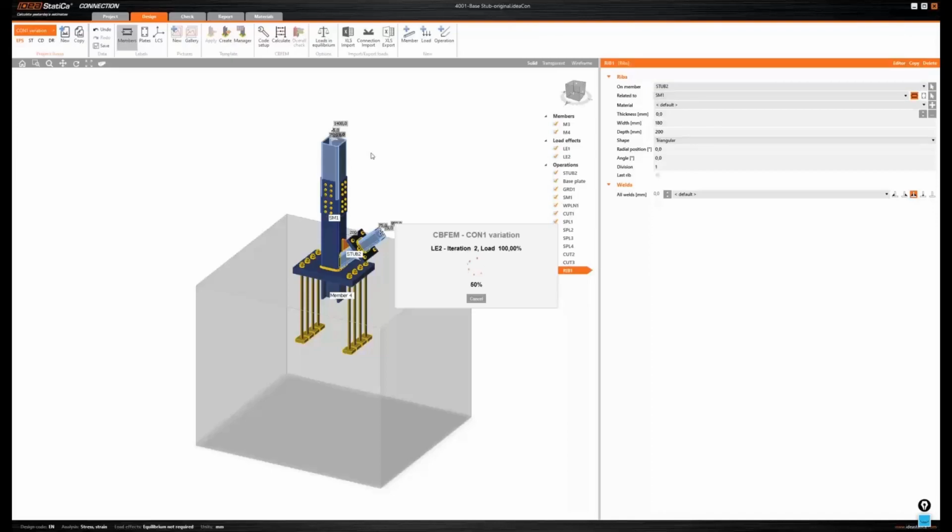Just something to add here. Specifically for this, it is really important that you use the beam links. I think the beam links can help you a lot, because the loads that are coming from another structural analysis software for the global structure are in equilibrium by definition. So this is the best way to ensure that the loads are correct, and you will not have any issues, as you mentioned, regarding which one is the bearing member. So as Kostis mentioned, it really doesn't matter if the loads are in equilibrium, and the beam links ensure exactly that.